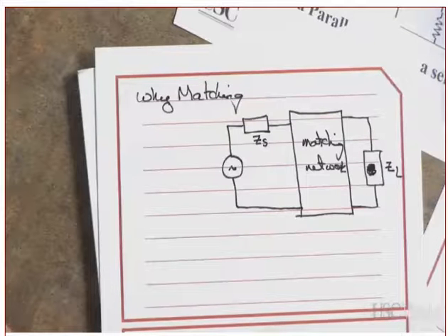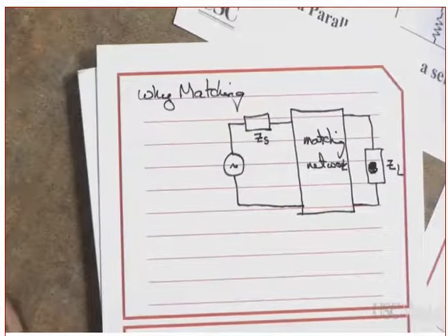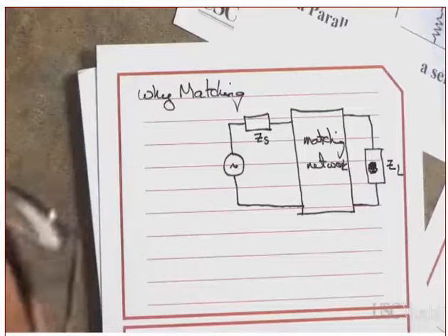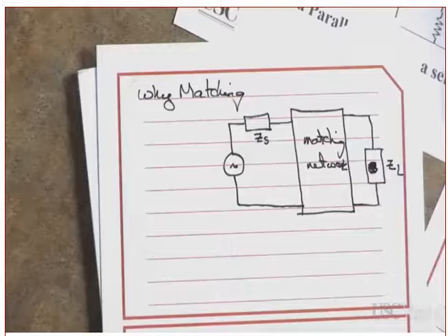The MOS circuit? If you remember, which I doubt, the input impedance of a common source amplifier is heavily capacitive. Yes or no? Which is what we refer to as CGS. CGS is the capacitance between the gate and the